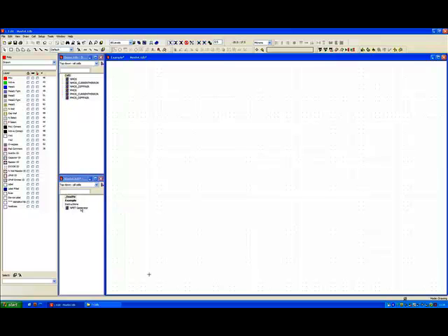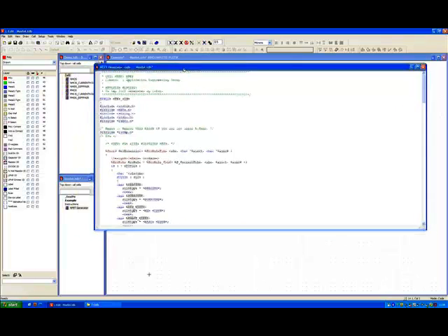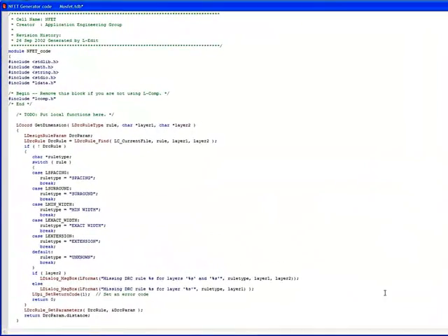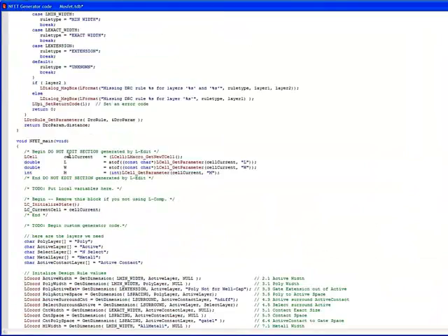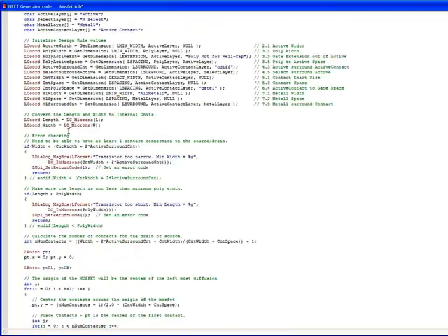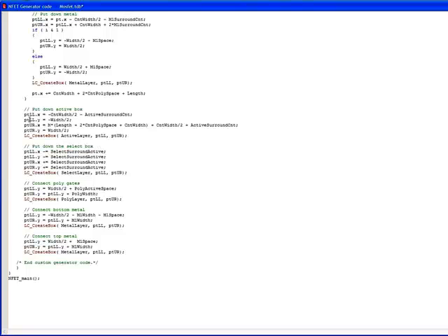In this example, I just want to show you a very simple MOSFET T-cell, which is a parameterized cell in the Tanner environment. What you can see from this window is that this T-cell is written in C. So there's an upfront coding cost that the layout engineer typically doesn't do. It's handed over to a CAD department. But this coding, in this case C, is very much tied into a specific vendor, which in this case is Tanner EDA, but also a specific technology node.